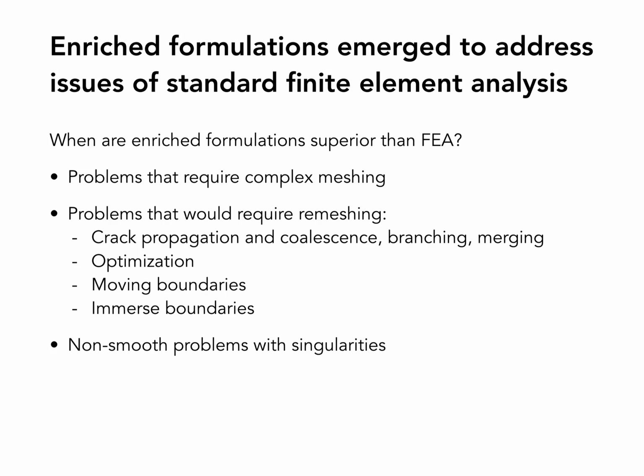Non-smooth problems with singularities are another one. You cannot really capture singularities with standard FEM. Even if you keep refining your mesh, you won't be able to capture the singularity because the functions that describe the singularity are absent.